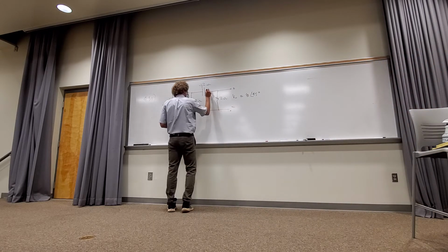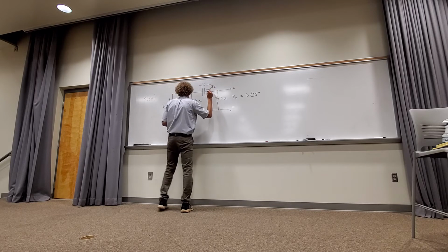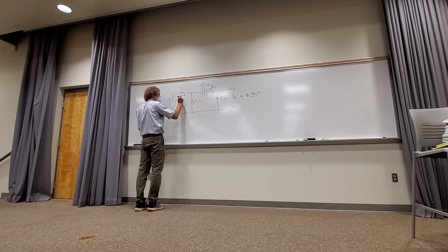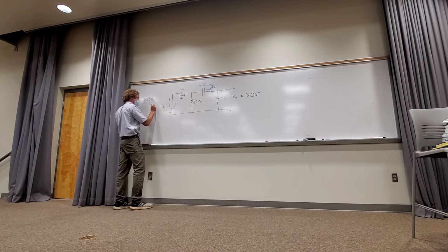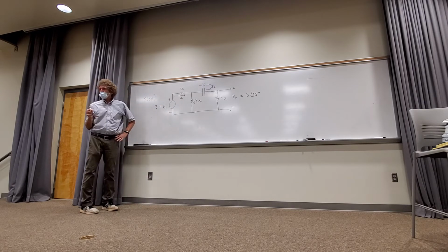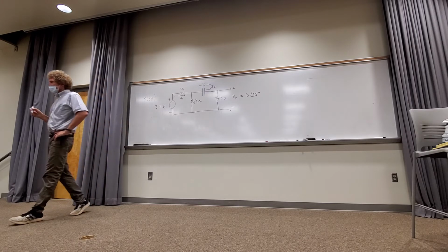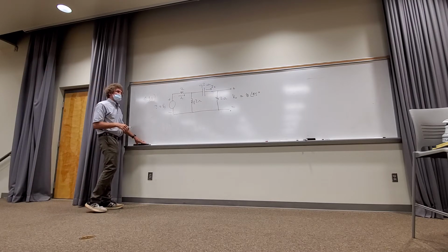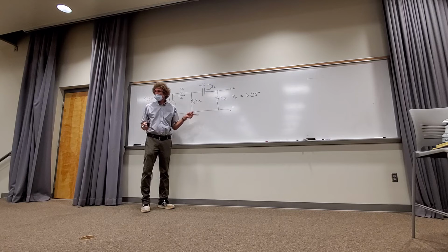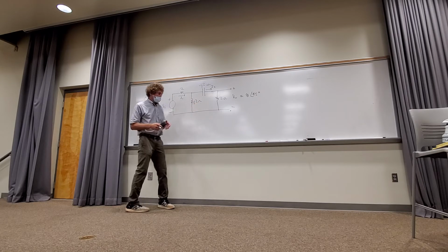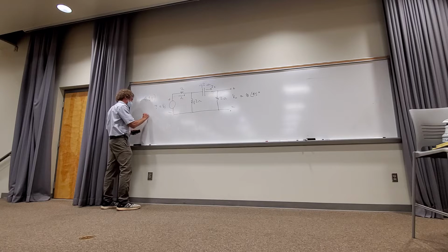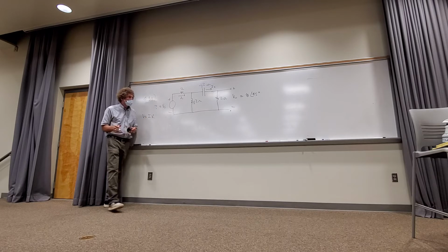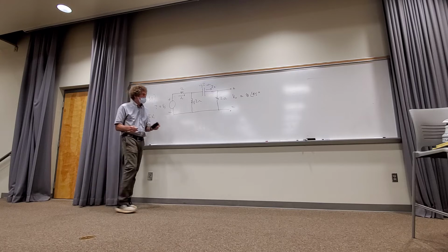He wants I2, I1, and Vs. But he gives you the output voltage. Now, you've got your tools, you've been taught the basics. So how would you get this? Think of yourselves as detectives. All right, if I have a voltage across any element, especially a resistor, do I have the current through that element? Sure, I know that V is equal to I times R, period. Right? Remember, these two are in series.